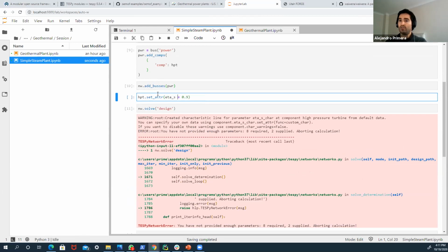Usually higher efficiencies, as in oil and gas, lead to higher investment, operational investment, or also capital investment in terms of redundancy of equipment. And in terms of turbines, if you want to have a high uptime, you may have to have a redundancy in terms of turbines. So for this type of project, that might be quite difficult to justify. But if the electricity price is high, then you can probably justify having redundancy and keeping, let's say, the uptime close to 95 or even 99%. But let's assume that this is 90%.